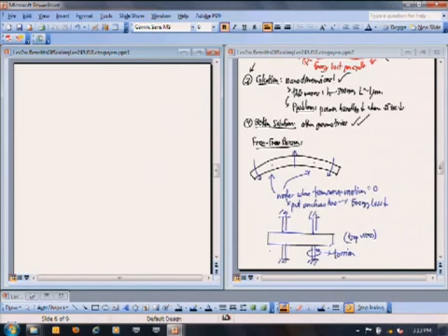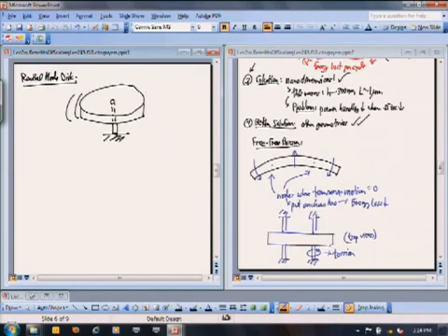and the solution that is probably going to be used most at gigahertz frequencies, is to really change that geometry. Use a radial mode disk. So now your resonator looks like this, and it's held up by a stem over your substrate. And the way that this actually vibrates is it expands and contracts along its circumference, sort of like a breathing mode. So if you make a disk like this that goes in a breathing mode, this point where it's anchored is a node.